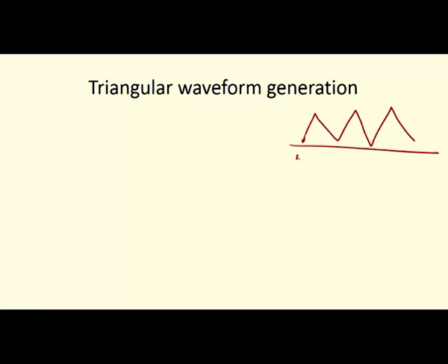The initial value is 00 first, then we have to increase to the maximum value, for which you can give the FF value. So, 00 to FF it increases, then it comes to 00, then again goes to FF. The same process we have to repeat to get the triangle wave. So, for that, what do we have to do?